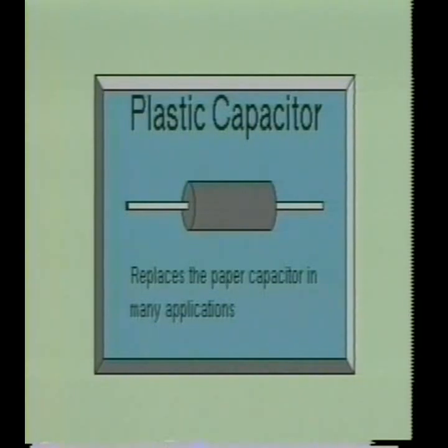This capacitor is plastic and has very low leakage. It is used in frequencies ranging from DC to 10 megahertz. The plastic capacitor is available in sizes ranging from a few picofarad to up to a few microfarad.